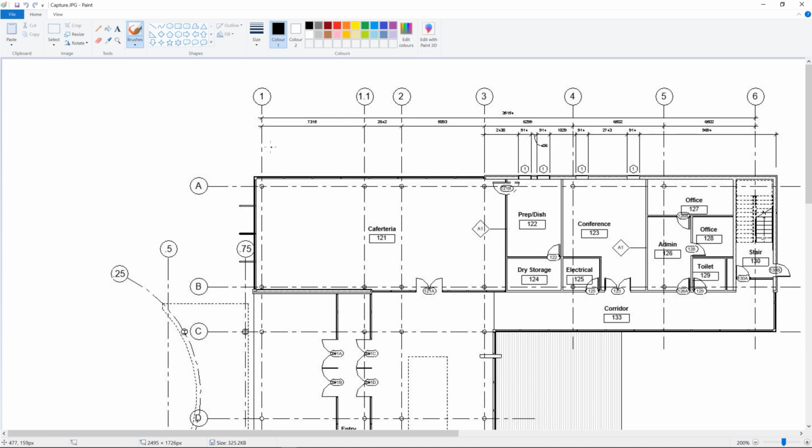So in order to get this into mobility simulation at the correct size, we need to find out what the pixel count is per meter. Okay, so that's what you'll have to do. You'll have to count these pixels to find out how many there are per meter, and you'll see why we need that in a moment.